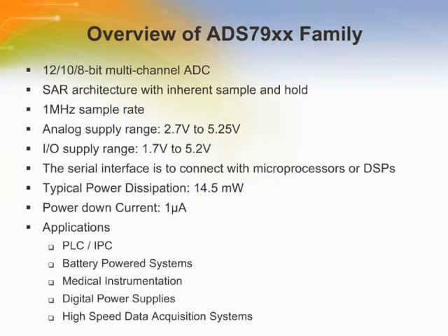The devices offer an attractive power down feature. This is extremely useful for power saving when the device is operated at lower conversion speeds. Very low power consumption makes these devices suitable for battery-powered and isolated power supply applications. There are 2 software selectable input ranges, 4 individually configurable GPIOs, and 2 programmable alarm levels per channel. These features make these devices suitable for most data acquisition applications.